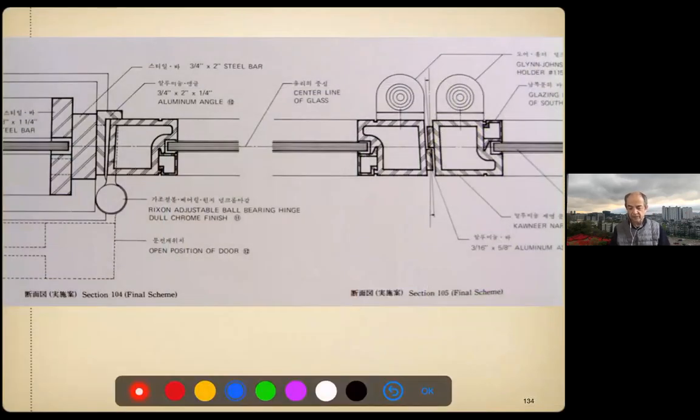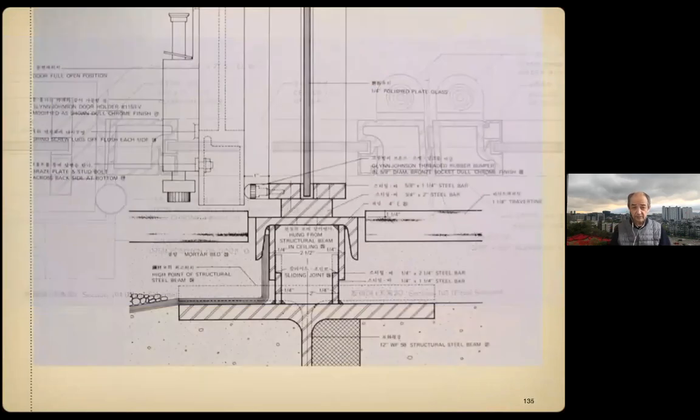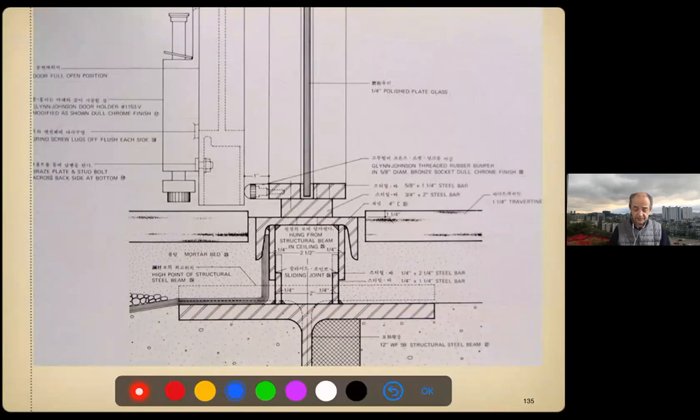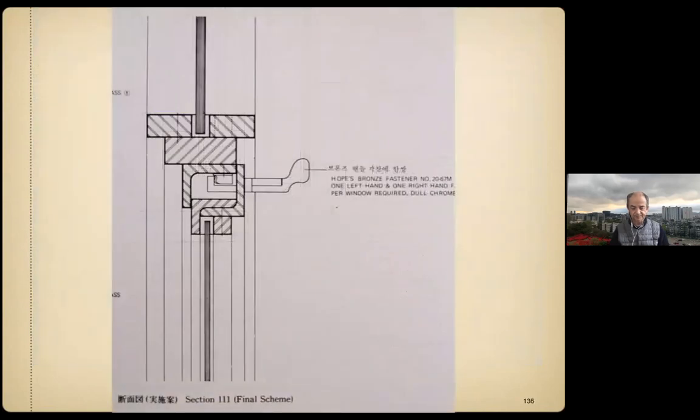Well, actually this is an aluminum door, but again, it's not a detail you can see. And interesting is this detail in which you have a sliding element in which, because the building is very light, the roof may have some kind of deflection. So you have a few millimeters for that door to move without getting totally stuck, right?